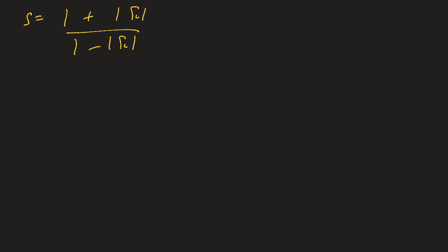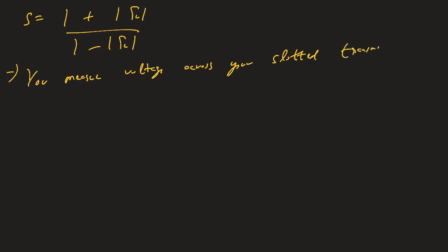And so what you do is that you measure voltage across your slotted transmission line, and you find Vmax and Vmin.